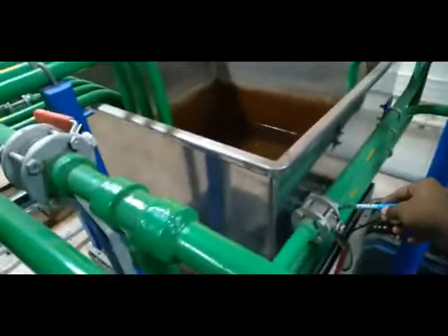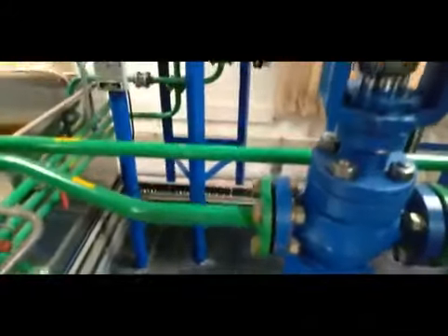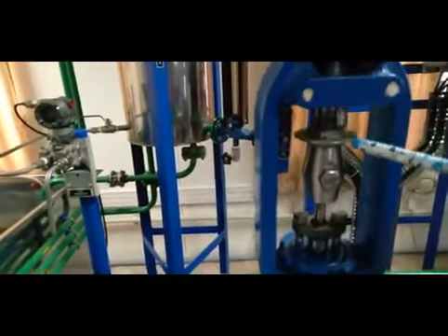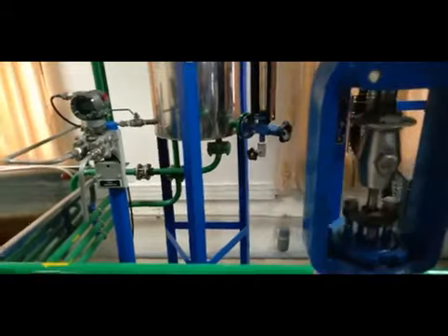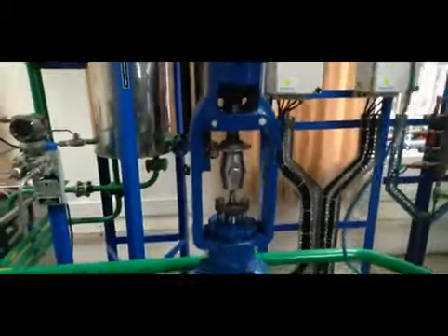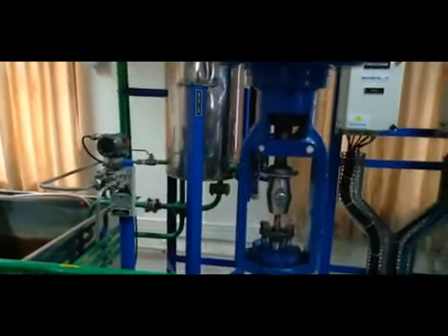This outlet is coming from the output of our tank. So this output will be coming through this control valve. You can see the valve action changing. So this valve will be closing because of the level rise in the particular tank. We are expected to maintain a 25 centimeter level.